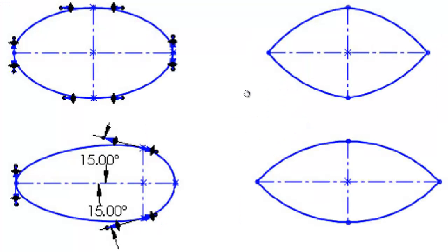The actual blade profile sketches that will fit best into this diamond pattern of guide curves can be something like an oval, a curvy diamond shape, a lenticular shape just made from 2 arcs that have coincident relations here and here to our diamond corner points, or even a teardrop shape which can fit into a diamond pattern which is asymmetrical.